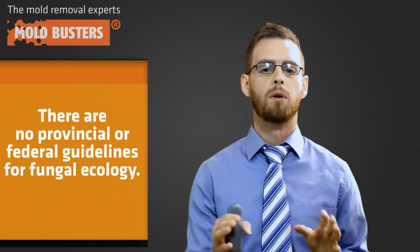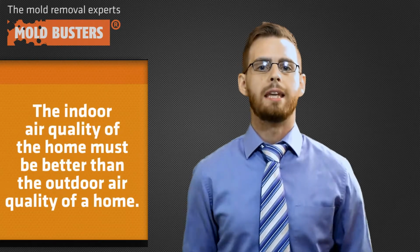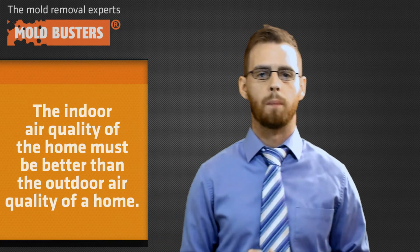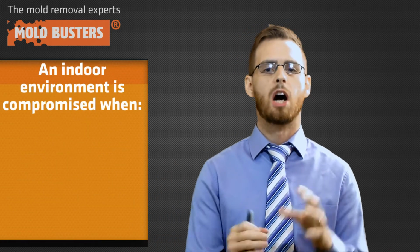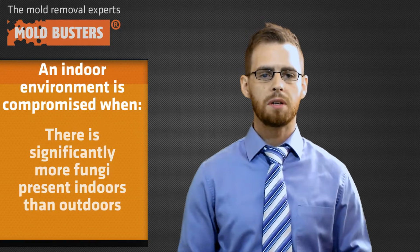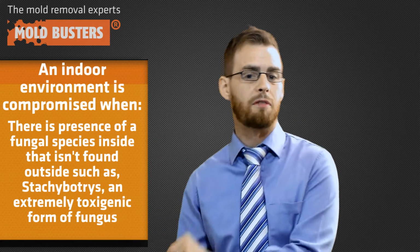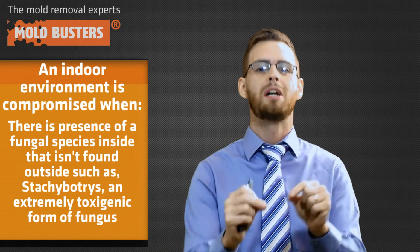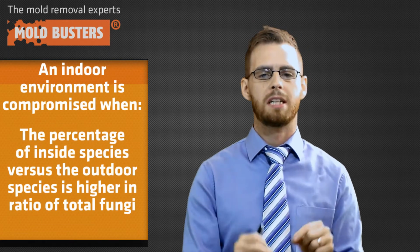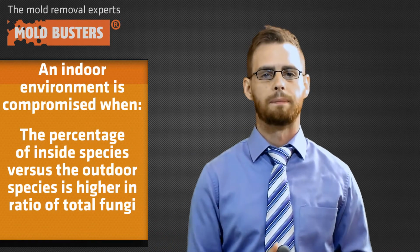There are no federal or provincial standards for fungal ecology. Basically, the indoor air quality of a home must be better than the outdoor air quality of a home. An indoor environment is compromised when there is significantly more fungi indoors than outdoors, where there's presence of fungal species inside that's not found outdoors, for example Stachybotrys, an extremely toxigenic form of fungus, and where the percentage of indoor species versus the outdoor species is higher in ratio in total fungi.